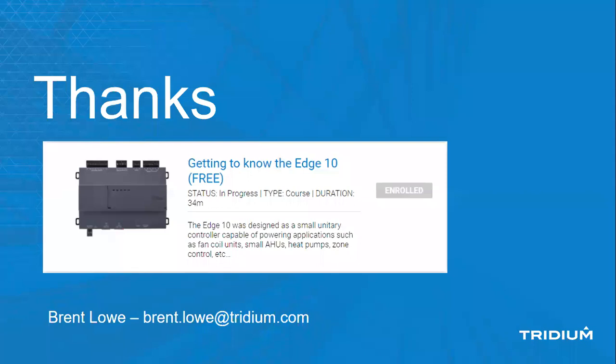Is Edge 10 compatible with the IOR16? Are there future plans for a smaller IO count add-on? Yeah, I get this question a lot. So we have been talking to the market about the IOR34 as being supported with the Edge 10. That is what we have tested with at this point, the IOR34. And the reason why we haven't been pushing the IO16 with the Edge 10 is because it would require a separate power source, which we thought would be cumbersome because it's 15 volt. In theory, it should work just fine, but it's not a configuration that we have tested specifically.